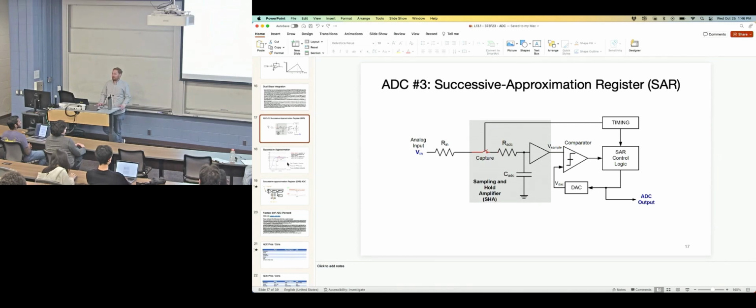So you're much faster, but you have to give up some size because that ADC is probably going to be large. The rest of the components aren't that big. The DAC is probably going to be the largest part. The comparator consumes energy, but there's only one of them, which is nice. The digital logic on chip is going to be pretty darn small, probably smaller than the comparator itself. And the timer associated with it is built into the digital logic. So the size things are really the DAC and maybe the comparator a little bit.